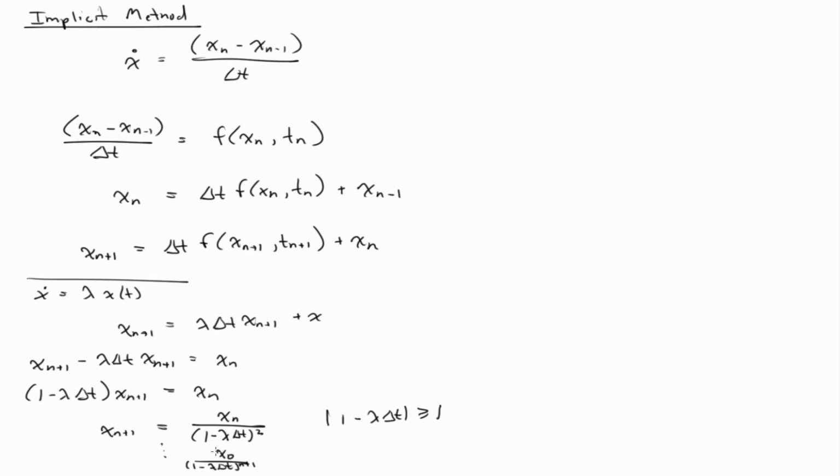So what we'll do a lot of times is compute it for a linear problem, and then because we really have a nonlinear problem, we just put a safety factor on it. So you compute the critical time step, and then usually something like 80% of that, so you have some reduction. That doesn't mean your simulation won't go unstable at some point. Sometimes it does. And I've had it happen to me.